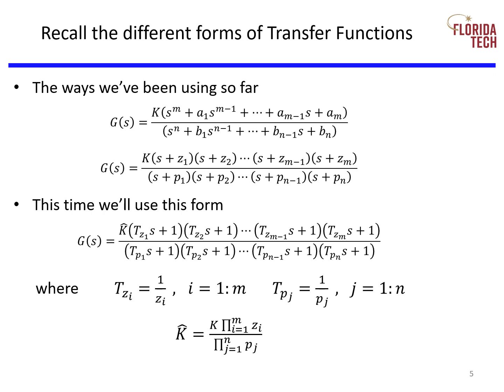Since all the z's and p's factored out are real numbers, the overall gain, or constant multiplier of the transfer function, is now the original gain, k, multiplied by the product of all the z's factored out, divided by the product of all the p's factored out. We'll use k hat as the new overall gain of the system, and the mathematical definition is shown, where the capital pi symbol means product. Recall that mathematicians use capital sigma for summation and capital pi for products.